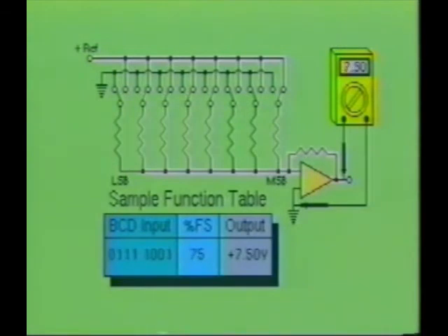The full-scale output voltage of this circuit is 10 volts, and the binary input code of this circuit is in the BCD format. As you recall, the BCD format only allows digits 0 through 9 to be expressed. Therefore, the percentage of full-scale voltage represented by this circuit can only be 99%. Since this circuit generates an analog signal of one polarity only, it is often referred to as a unipolar digital to analog converter circuit. There are, however, DAC circuits which produce analog outputs in both the positive and negative sign. These circuits are often referred to as bipolar digital to analog converters.